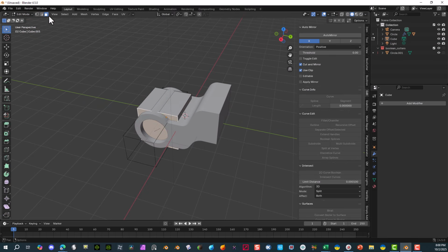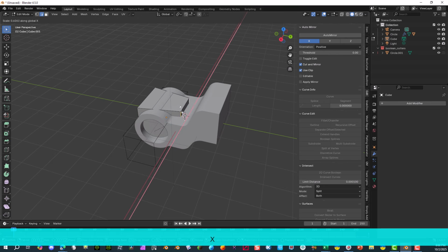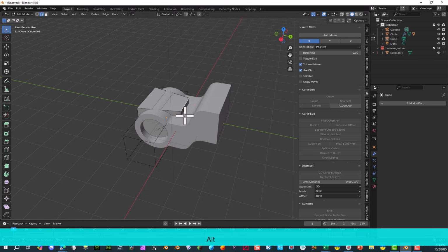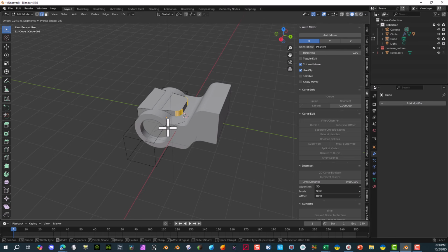And I'm going to select the very edges on each end. Actually here I just used the S key to shrink it in together. And now I'm going to use the same thing. Select them both again and hit Control B, so I could add a nice little fillet around this, or round bevel. So there we go.